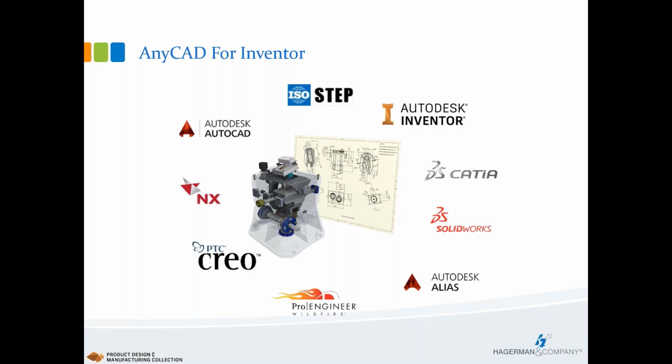The way that works is, say I'm using Inventor 2022, so these files are saved as Inventor 2022 format. Anyone that's using Inventor 2021 with the latest Update 3 could place my Inventor 2022 file inside Inventor 2021. So it can go one release back. You can't edit it, but you can place a live reference. So AnyCAD also works for Inventor one release back.